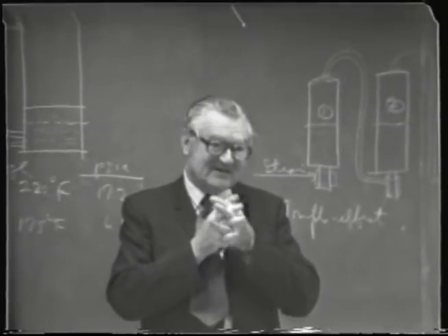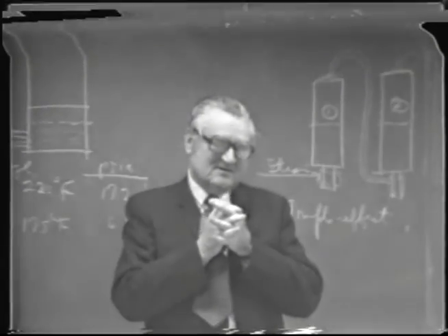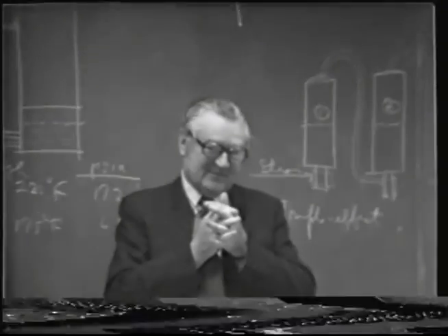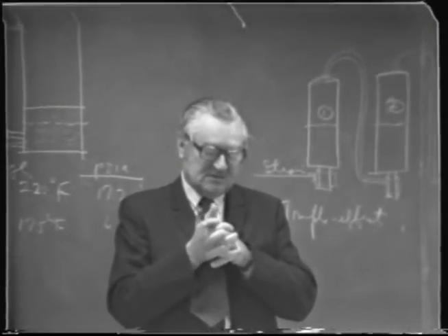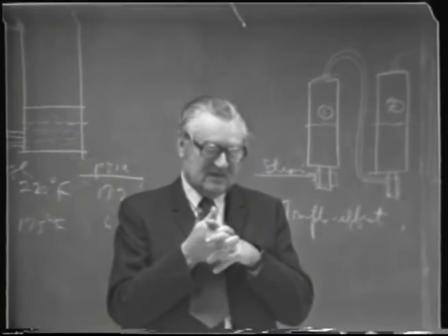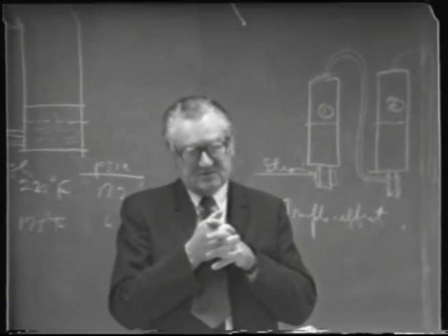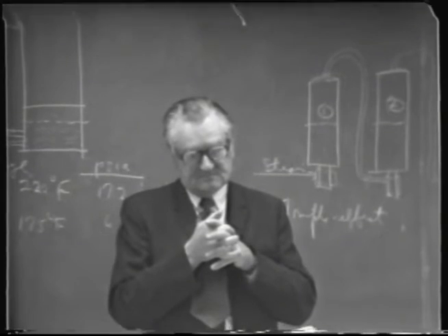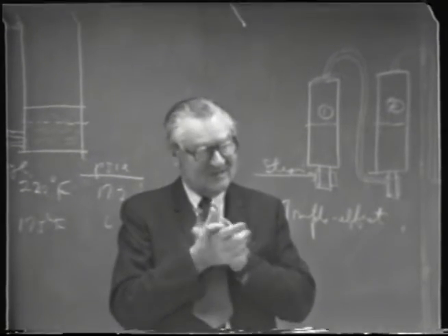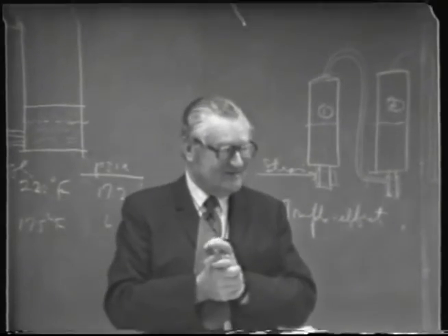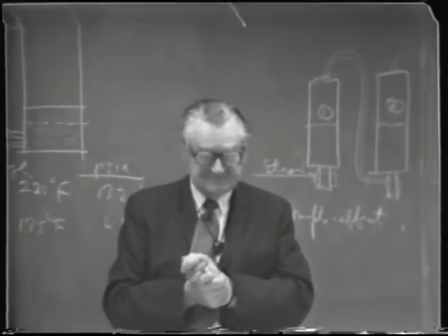In other words, that energy will still be retained, so that the vapor going into the bottom of the column may be slightly superheated, or at a slightly higher temperature than the pressure at the base of the still. But if so, it'll just help vaporize a little bit more of that liquid, so it'll soon come right back down to the saturation temperature.